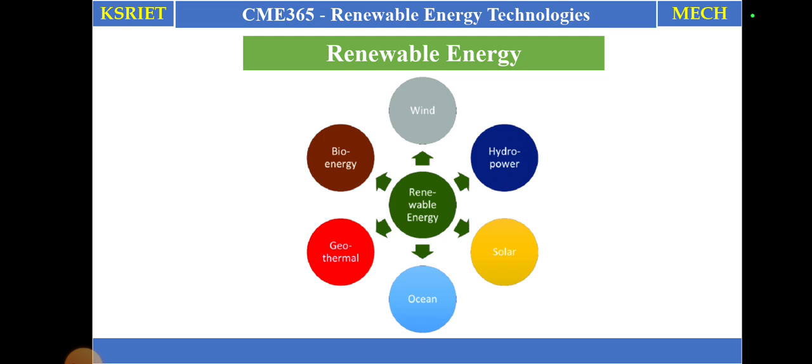Then tidal energy. Tides are generated primarily by the gravitational attraction between the earth and moon. They arise twice a day, mid-ocean. The tides range only a meter. Basically, in tidal power, water at high tide is first trapped in an artificial basin and it is allowed to escape at low tide. The escaping water is used to drive the water turbines, which in turn drive electrical generators.